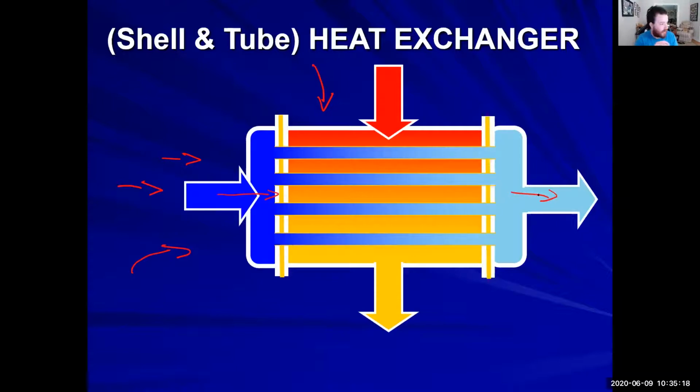We don't need to use any mechanical pump at all. It's just a giant valve that opens up, and we just start taking in water. All right. So we have two things that can be pushing salt water through this main condenser: either the main saltwater pump that we have, or we can use a scoop.